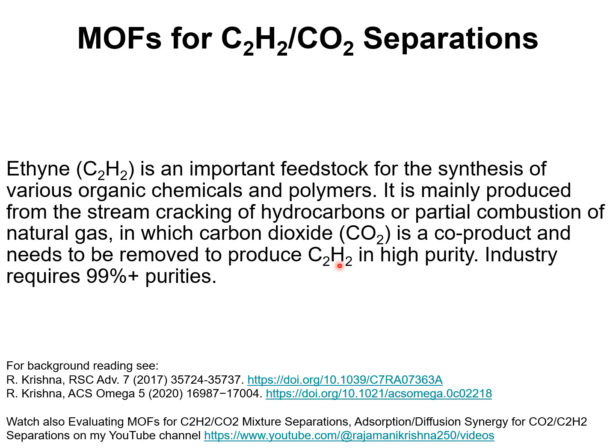C2H2 that is desired by industry. Industry demands C2H2 purities in excess of 99%. And in this presentation, we examine pressure swing adsorption technology for C2H2/CO2 separations and how to evaluate MOFs for use in such PSA units.